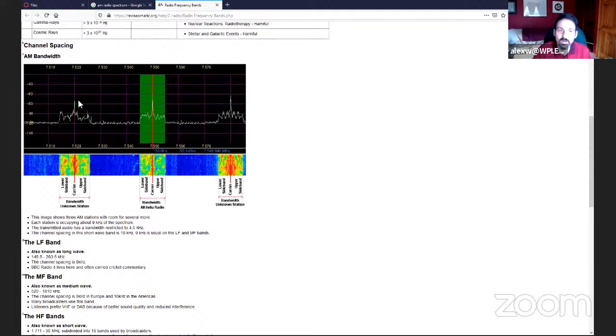That is the AM radio spectrum, right? So there's a spiky thing in the middle. That spiky thing should be smack dab on FC. So in terms of locking, it's great because you can tell where that signal is precisely. You don't have to figure out whether it's 50-50 or a little bit over there. There's no uncertainty where that delta is because it's half of the magnitude response in terms of height, okay, for that AM transmission, right?